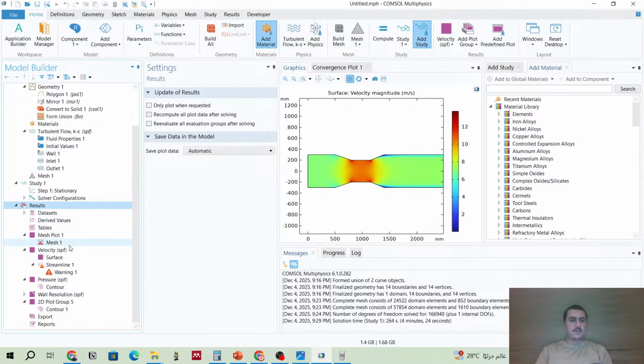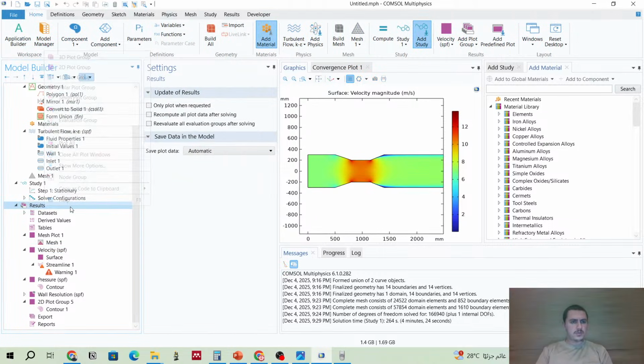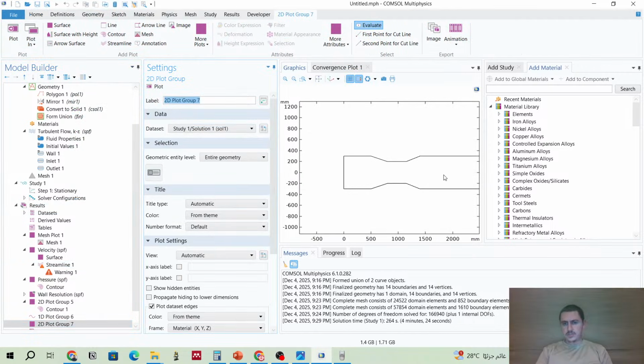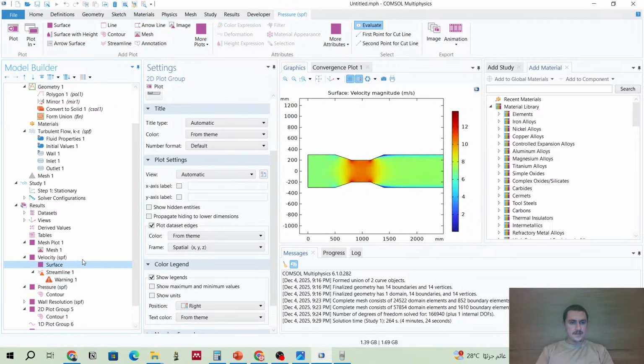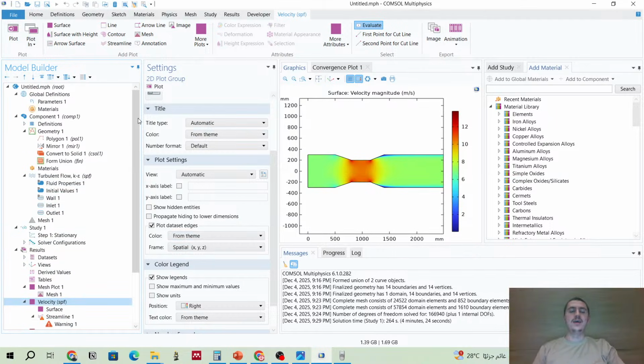We solved it here. We can do some post-processing, but as I said, you can have a 2D plot, or a 1D plot. I want to see how velocity changed along the x-axis, but I still need time to learn post-processing here to do it better. But we actually need the velocity contour and pressure contour, the most critical things. The other parts of post-processing, we will do in other videos. But for now, I'm happy that we modeled a geometry and solved a complete COMSOL problem.